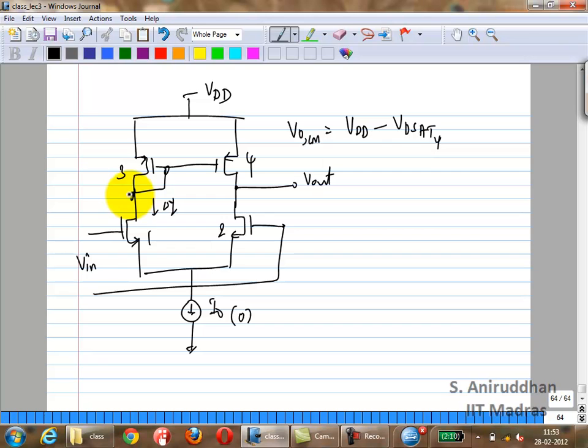Right? You actually know how much it's going to change it, because it's just going to change it by delta I times 1 over Gm and you're done. And 1 over Gm is quite small. Correct? Whereas here, it can actually change quite a lot. And if you really build a real circuit, it will probably go to one of the rails depending on the mismatch. Okay, the output impedance is probably going to be high enough to send it either very high or very low. And the same thing goes without saying for the cascode also.